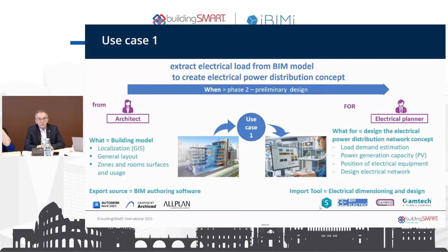And as an electrical planner, I have to design my electrical network. So as an electrical planner, I need to be able to identify the load demand of the building. Here it's about the usage: the number of square meters for meeting rooms, the number of square meters of kitchen, the number of fan coil units or things like that. I need to sum up the demand load.